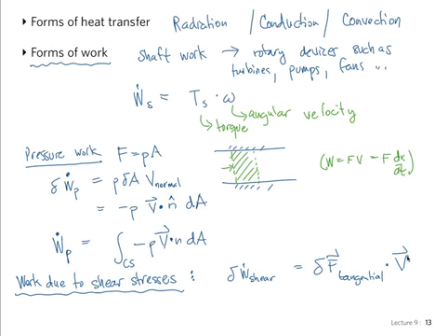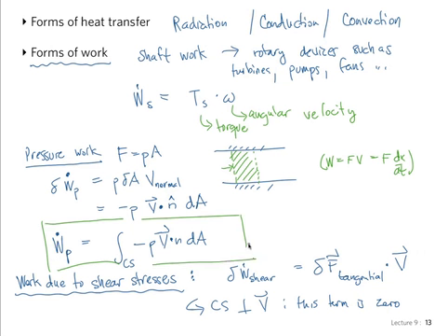But with our usual approach of always selecting the control surface to be perpendicular to the velocity, then the tangential force is always going to be 0, and so we don't have to worry about this term, which is very useful. So with control surfaces perpendicular to velocity, this term is 0. But this one is going to be important: the work due to pressure in the fluid. And this one also for any rotary devices, which we will often have.